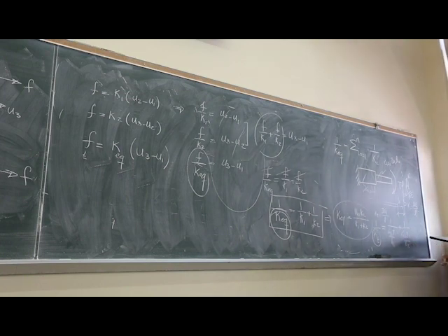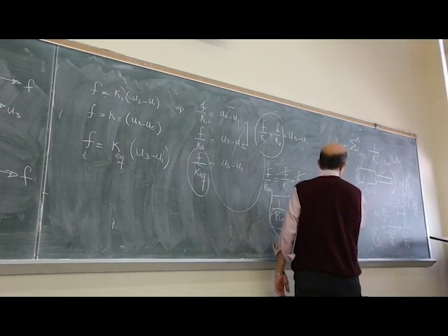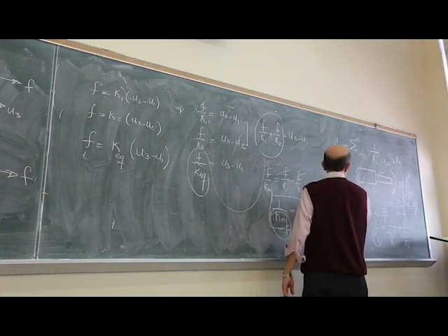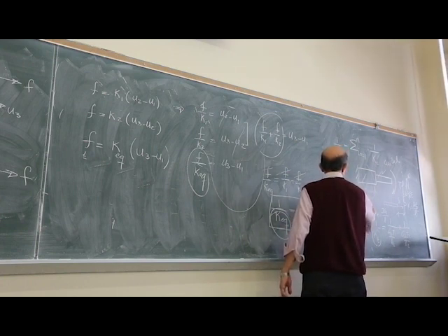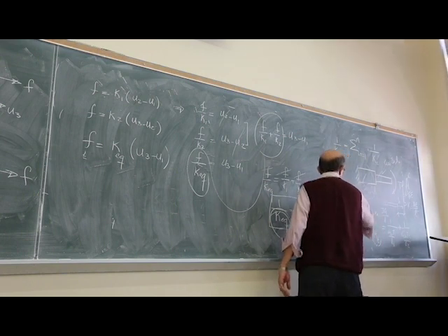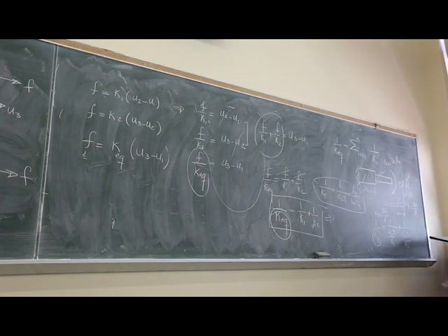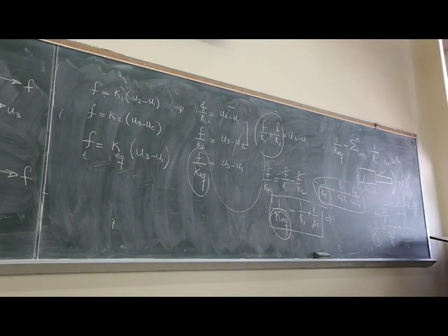Or you can simplify that as 1 over KT would be L1 over G1 J1 plus L2 over G2 J2. Of course, you can further simplify that, but that's how you find a single shaft that can replace those two. Okay?